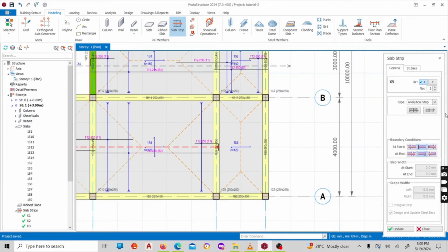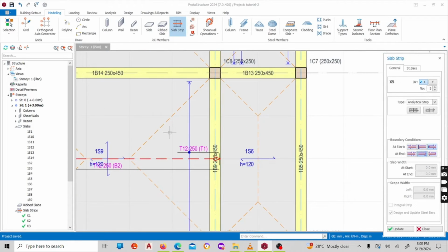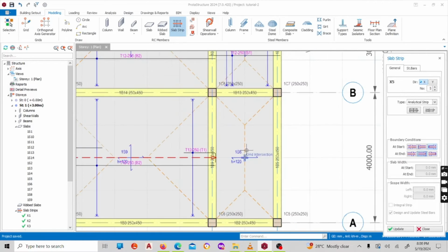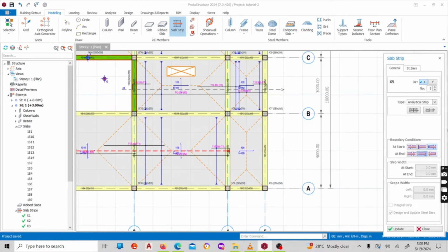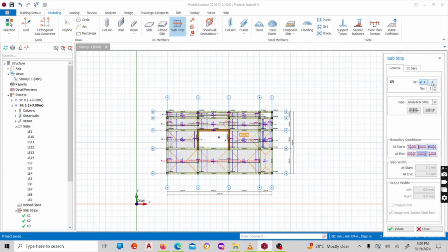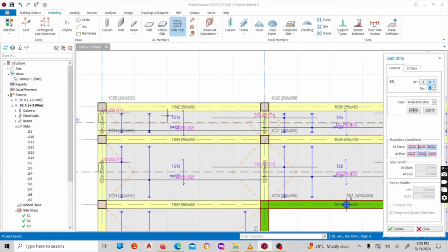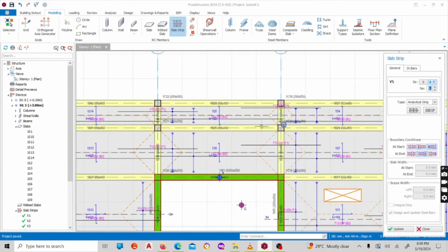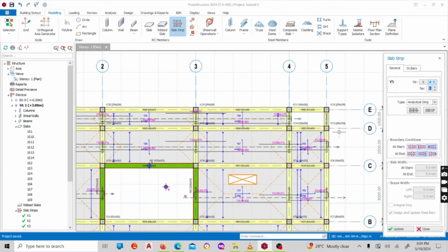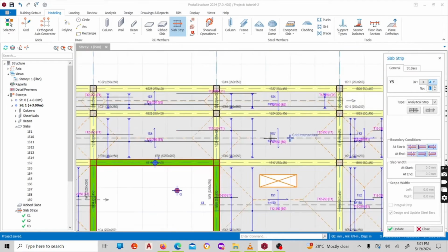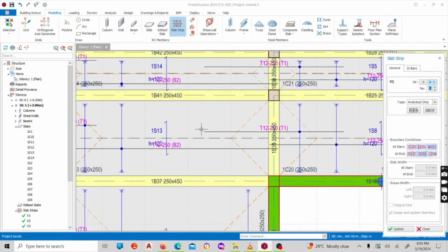And then from this part here, I will select, we're coming from a slab going to a beam, because this end has a beam. Remember now this is in the y direction, so the x direction is done. So I come here and change direction to y. Now I told you all this is one-way spanning.